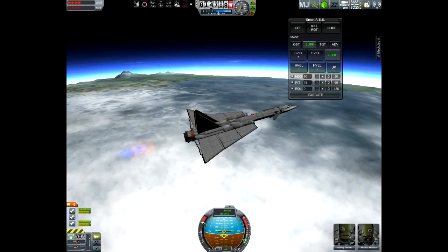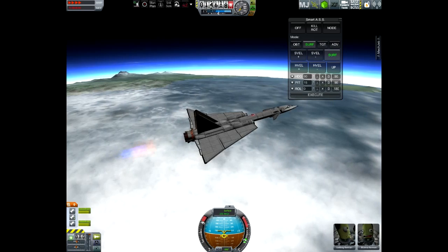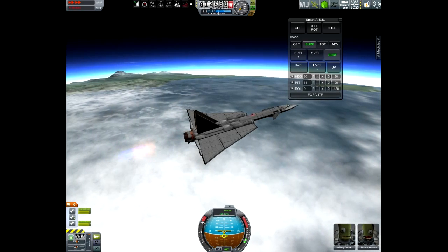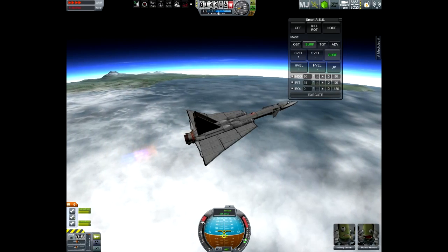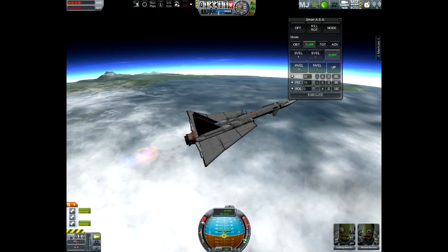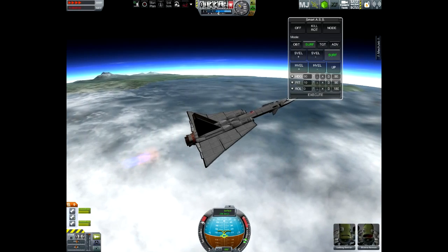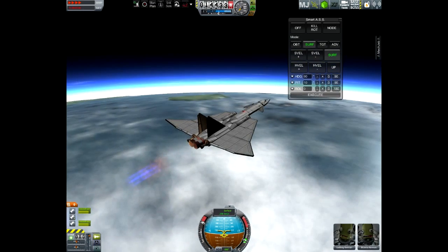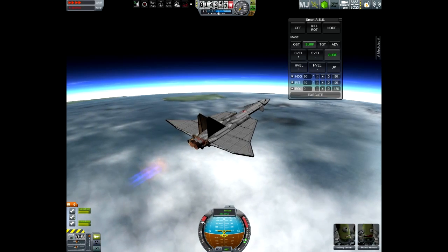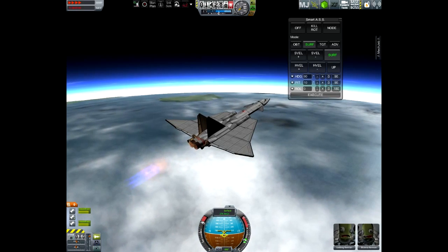So there we go, we reached our, let's say, ultimate altitude for the Whiplash engine. It's around 15,000 meters. Now I will try to accelerate, to provide us with more speed. I'll set the pitch to 10 degrees. We might lose some altitude for now, but we will cover it up once we start accumulating more and more speed. Now as you can see, we are accelerating at 1G